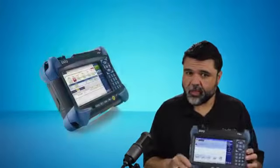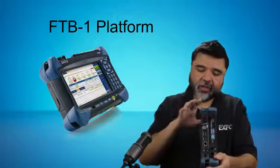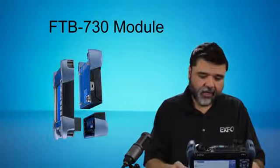So I want to talk about, or actually I want to show you some of the things that I've talked about: what connectors look like on an OTDR trace, and what a connector end face looks like with a video inspection probe. I will be using EXFO's FTB-1 platform. This is the platform here in the front, and on the back is a module. The module that I'm using today is the FTB-730. This particular unit has an in-service OTDR port as well, which is why you see the second port.